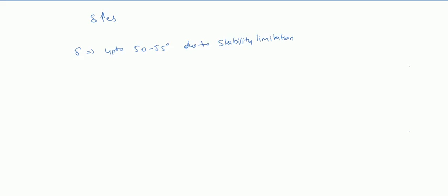Now there was objective 2. Objective 2 was what? Objective 2, that voltage regulation of the transmission line should be minimum or zero. So voltage regulation कैसे निकालते हैं हम basically? Voltage regulation of the transmission line, if we see, the voltage regulation is given by Vs by A minus Vr divided by Vr into 100. This is percentage voltage regulation basically.